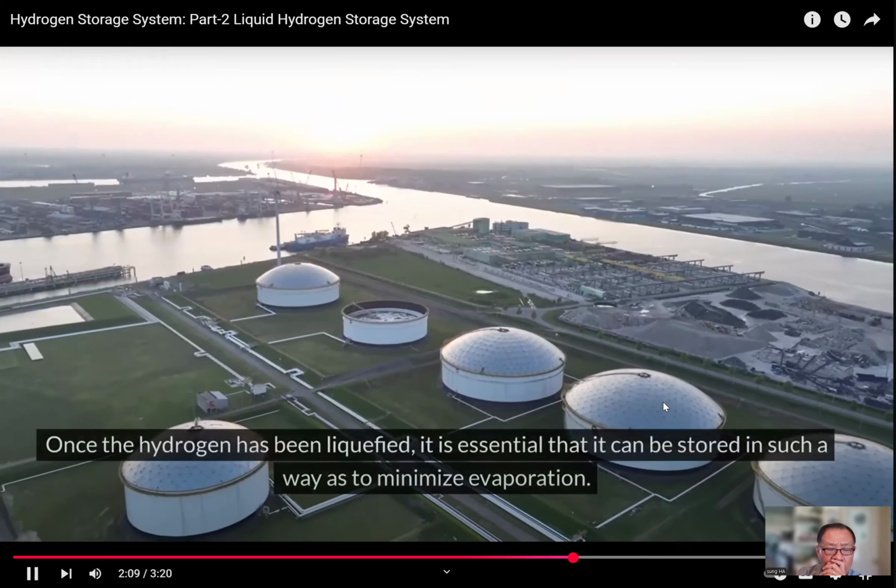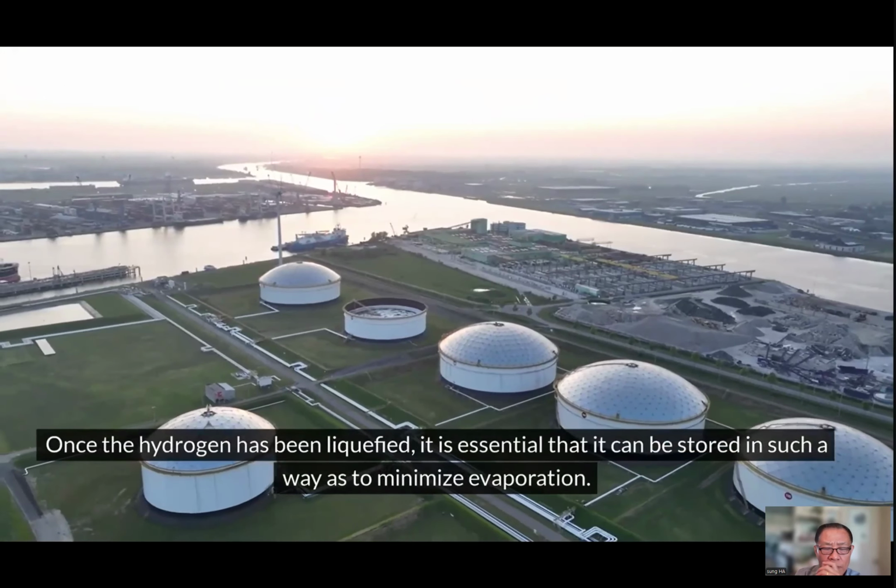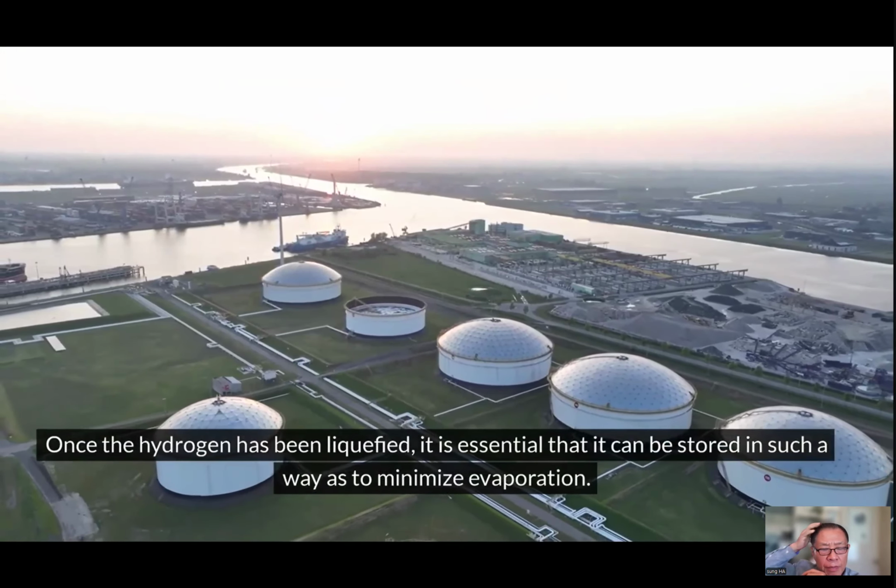Once the hydrogen has been liquefied, it is essential that it can be stored in such a way as to minimize evaporation. This evaporation of liquid hydrogen is not only a loss of the energy invested in liquefying the hydrogen, but also a loss of hydrogen in the long term, as the evaporated gas must be vented due to the pressure accumulated inside the storage vessel. This loss of stored hydrogen over time is known as boil-off and is reported as the percentage of stored hydrogen lost per day, the boil-off rate.